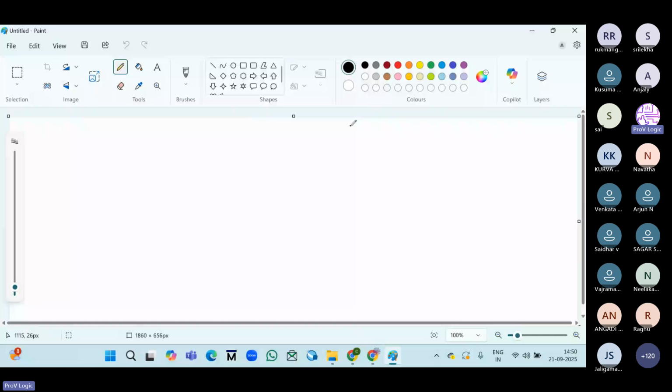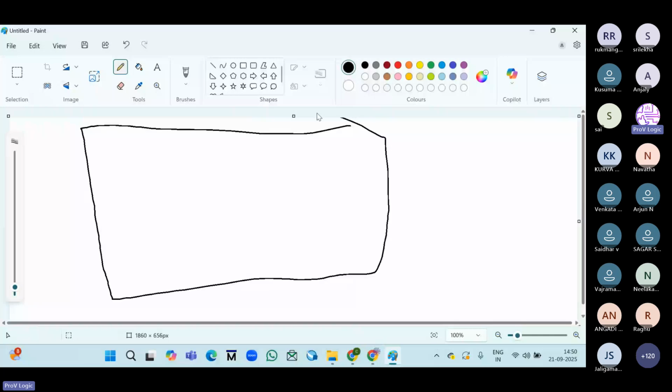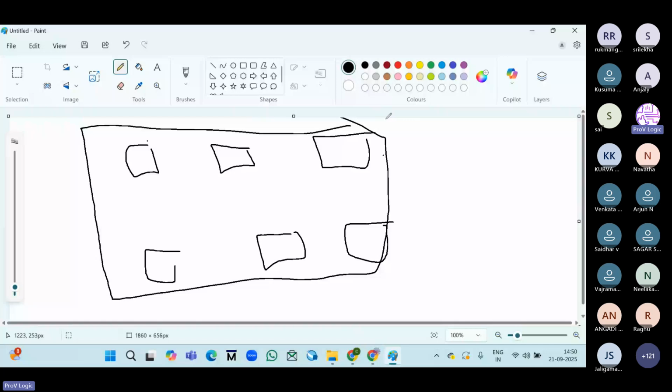This is the hardware SoC. Here I have GFX blocks: GFX, DFX, NBIO, SBIO, PCIe, AXI. These are some blocks I want to verify. There will be a bus connection, a debug bus connection. Through this, the debug bus units, we will connect these all in a cross trigger network.